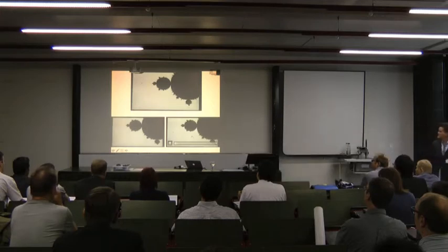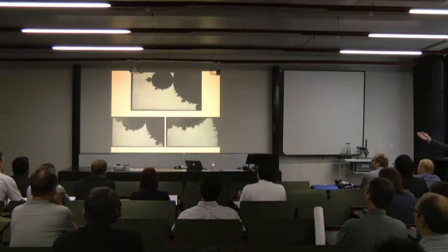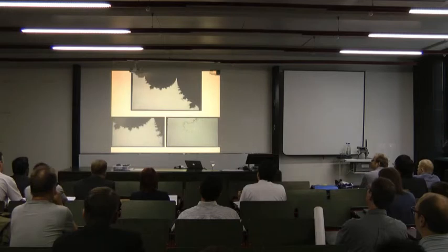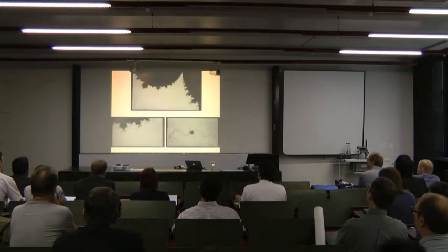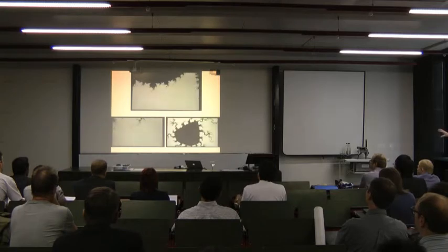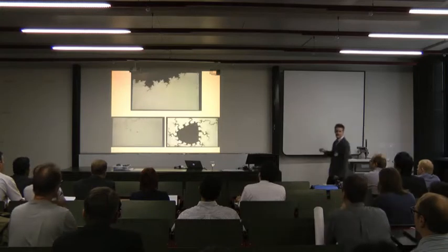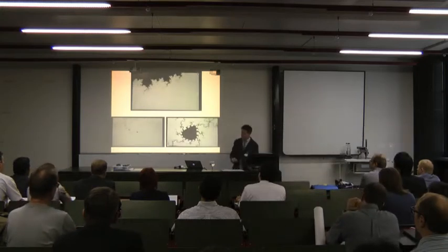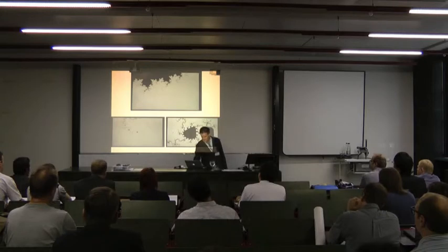On the top there is the 800 megahertz ARM. Lower left, vanilla high-level synthesis where we didn't set any constraints. Lower right, where we applied loop pipelining, okay, in the high-level synthesis. And this is just one high-level synthesis circuit that's doing that. Okay. You can actually see huge speedup over the 800 megahertz ARM for a certain kind of application. Okay.